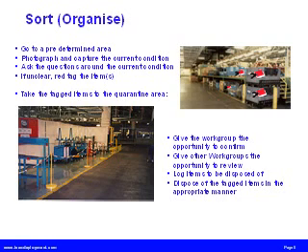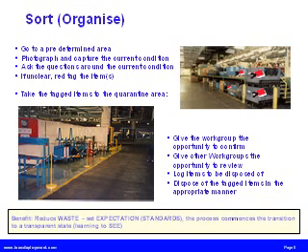So having conducted the audit, or during the audit, if it's at all unclear why something is there, you tag it. Take the tagged items to a quarantine area. Don't simply get rid of these. The reason for this is to give the appropriate work group a chance to investigate why the item is there. It could be a vital tool and something that you're unaware of. Once this has taken place, simply record all items to be disposed of and then remove them in the appropriate manner. The benefit of all this is a clearing of the decks. You are setting a standard of housekeeping within that area.